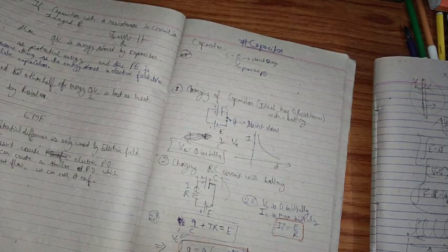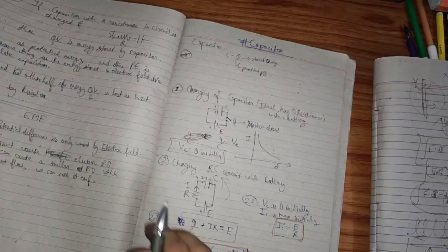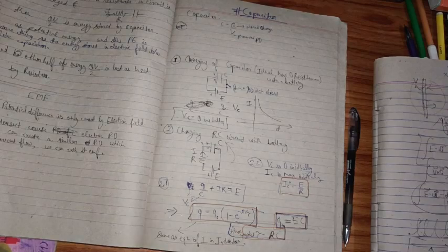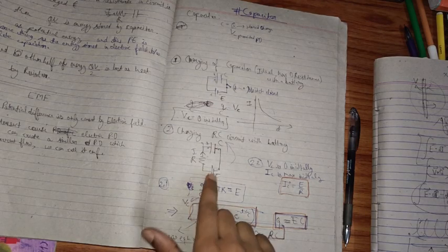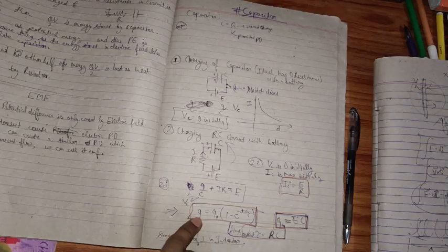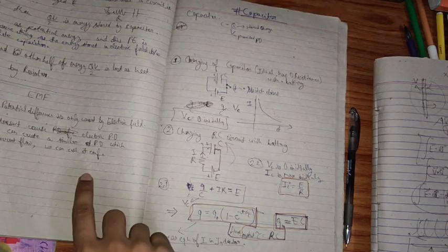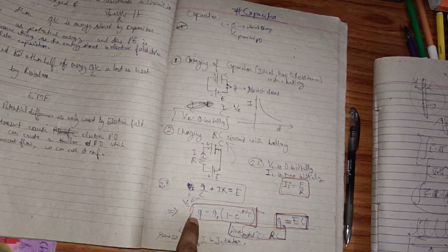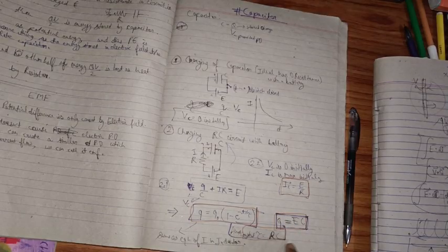Okay, in these capacitor equations, we have to memorize this equation: Q is equal to Q naught times this. Just like the equation for I, we have to memorize the equation of Q in this case, and differentiating Q with respect to time, we can get the equation of I, and Q by C gives the voltage, and the time constant is RC, and that's it. I C naught is equal to E by R. Now the discharging case is not given here, but can be simply derived, like here we have this equation, writing this equation and solving it.